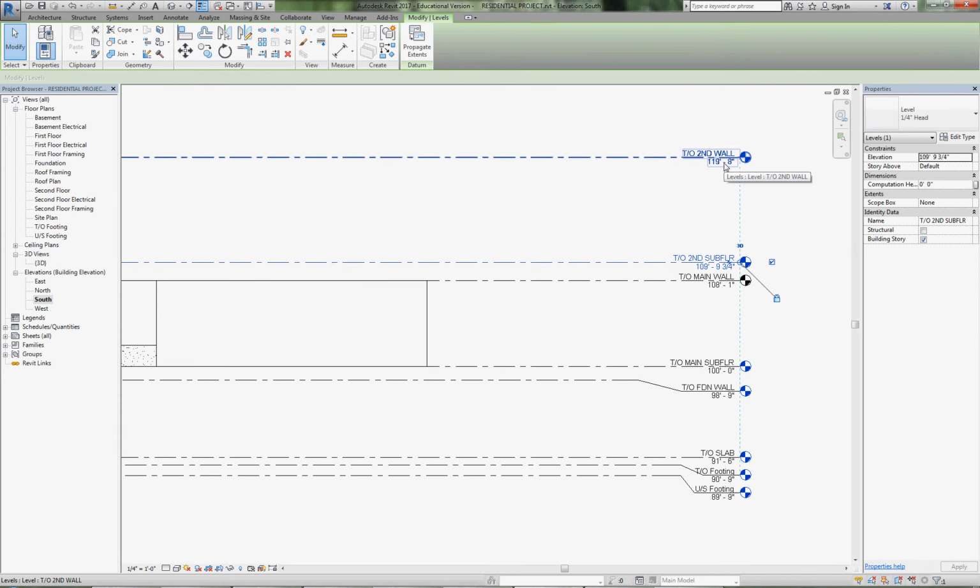Now these spot elevations are all figured out ahead of time on a piece of paper in our preliminary stage. So I've got them all written down in front of me here. So that's how you would approach it. You're not going to just think of it now as you're sitting here. So 109 9 3/4 plus 8-foot 1 is 117 feet 10 3/4.